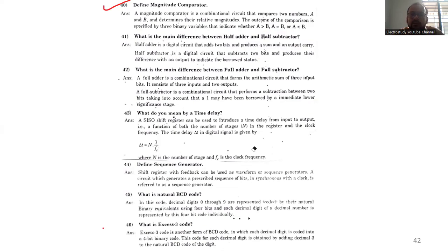A trainer kit will be available. Identify and refer to the pin-out, and accordingly connect it. Correct. ICs like 7404, 7408, 7400; you have to find them out based on the gate. I think you are recalling whatever I explained.